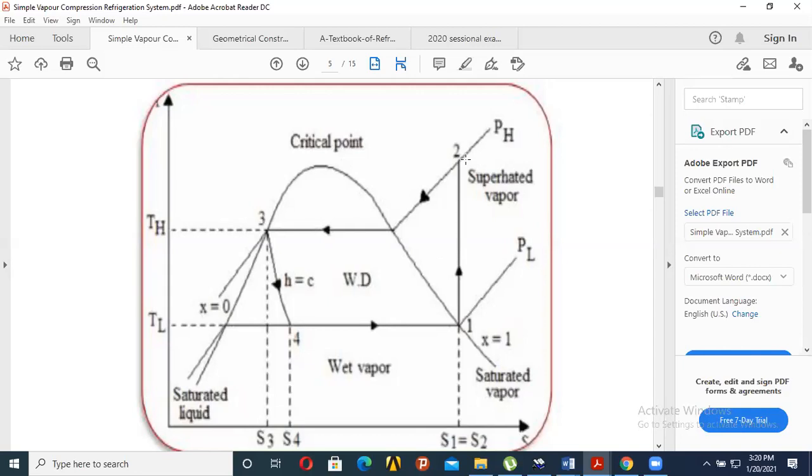So the condenser now is brought in. You employ the condenser now to start cooling this. Okay. So you can see this is the same pressure, but the temperature is different. As you are cooling, you reach a point which we call a dew point, meaning it is initially gas, completely vapor, but you are cooling it, and then eventually there will be some drops here. That's why we call this point a dew point. This now becomes a mixture of liquid and vapor until it eventually reaches what? Liquid.